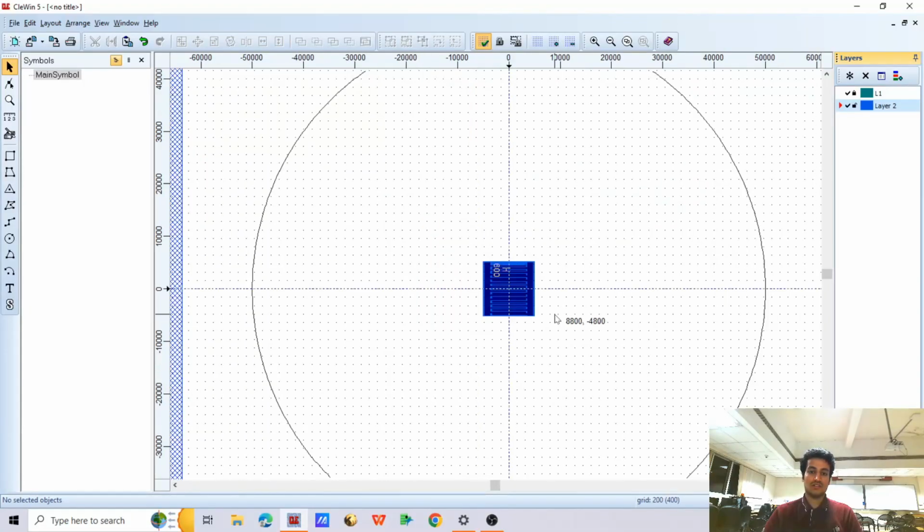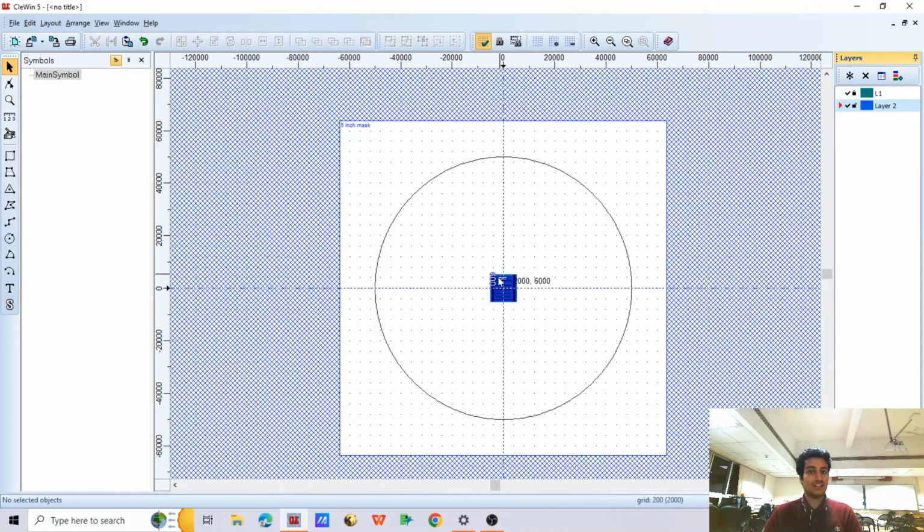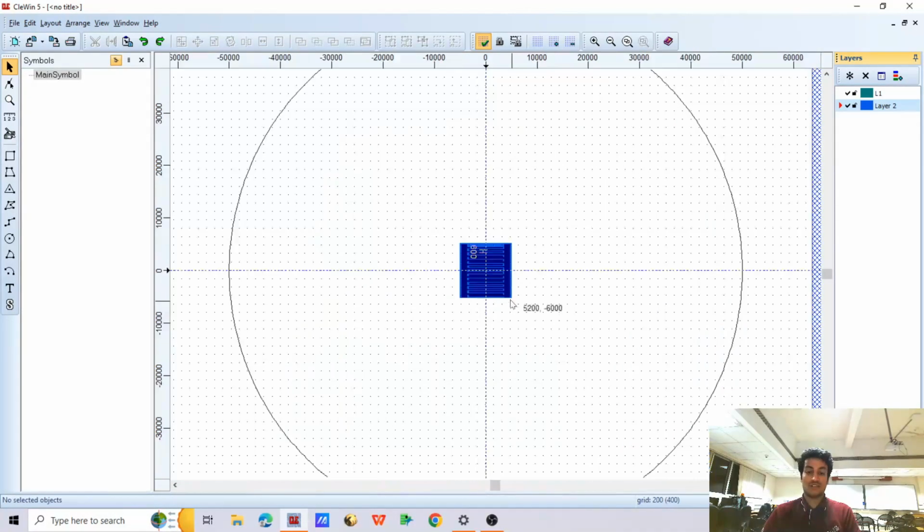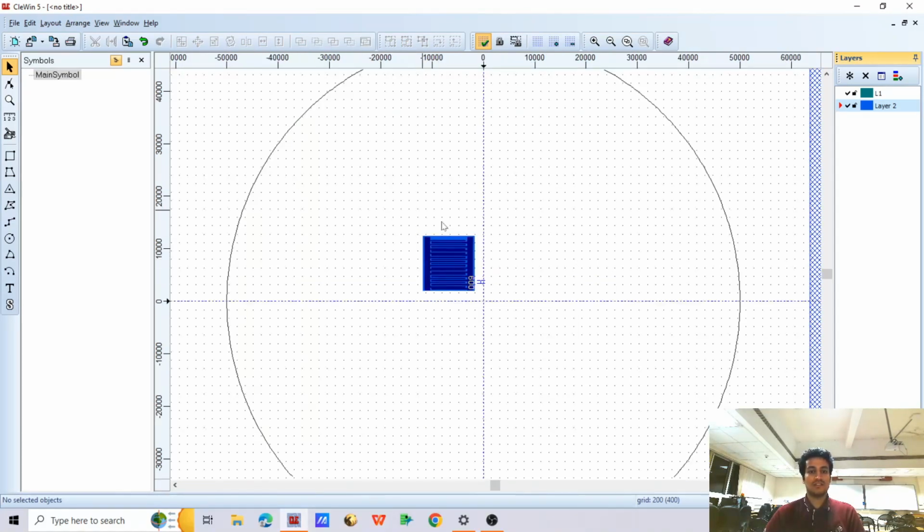Just suppose I want this device design in the full 4-inch area, so I will move it a little here, then I will populate in the full 4-inch area. Okay, so I have a lot of ways actually. So what I can do is, first I will populate this in this full quarter, then I can copy this quarter and then mirror it in the nearmost right side quadrant.